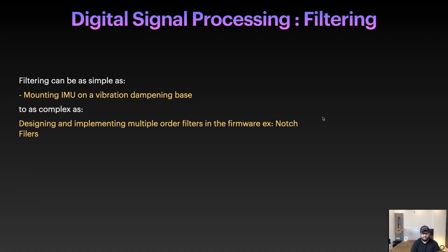Similarly, you can use a low-pass filter that will filter the high frequencies. When I talk about noise, these are generally high frequencies in the system. So you can design a low-pass filter that will pass the low-frequency signal and block the high-frequency signal.